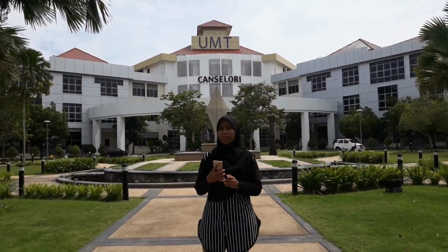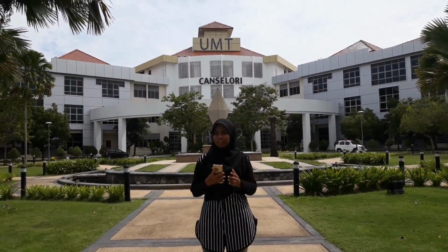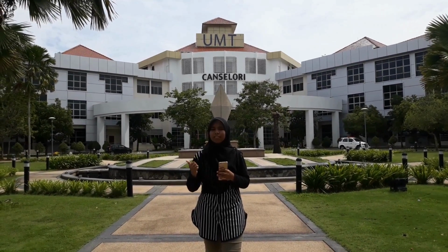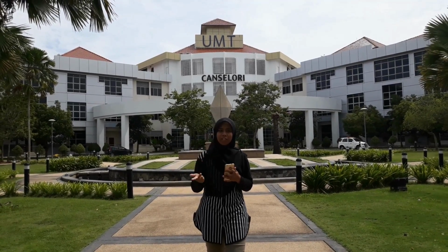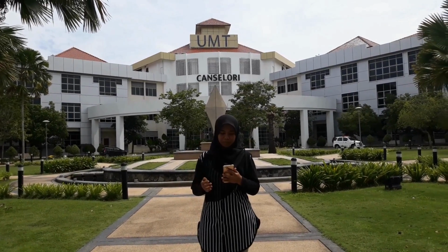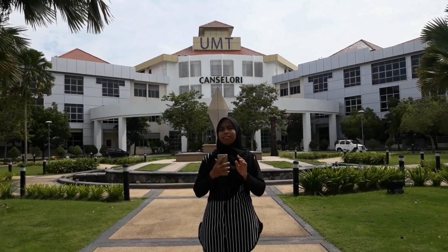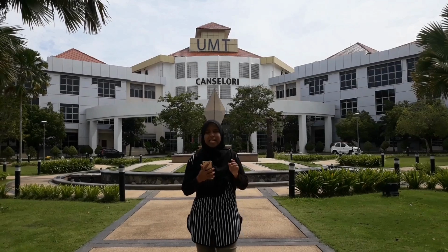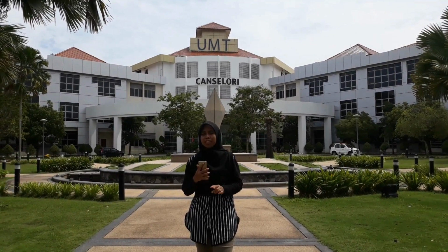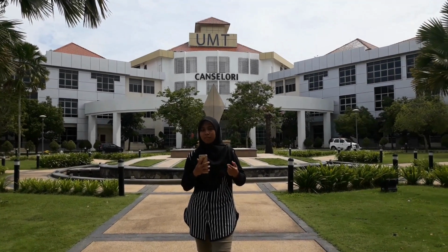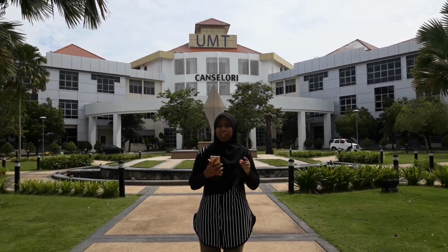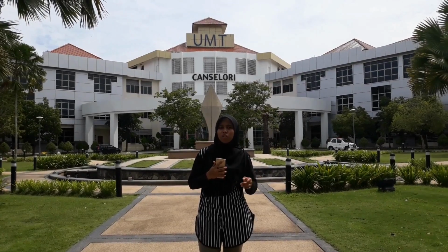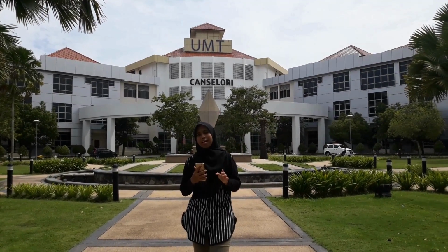Next, grit chambers are long, narrow tanks designed to slow down the flow so that solids such as sand, coffee grounds, and eggshells will settle out of the water. Grit causes excessive wear and tear on pumps and other plant equipment. Its removal is particularly important in cities with combined sewer systems, which carry a good deal of silt, sand, and gravel that wash off the streets or land during a storm.